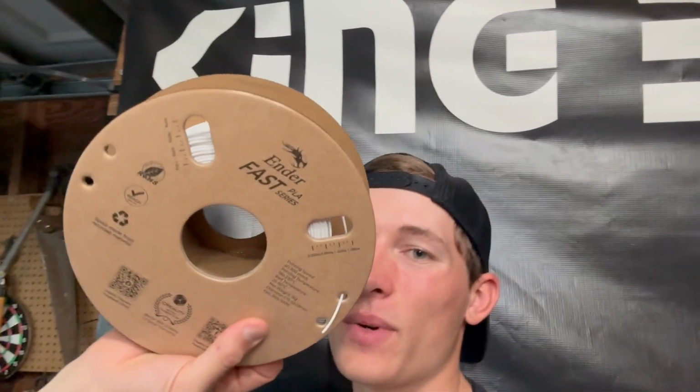Now what you gotta do is you gotta set up your 3D printer. So different filaments, these rolls, they're called filaments. It's the material you use to 3D print. They melt at different temperatures. PLA, this one says on the box, 190 to 230 degrees Celsius is what this usually prints at. So if it's a faster 3D printer, you put up the temperature higher. If it's a slower 3D printer, you put it on the lower end of that spectrum.